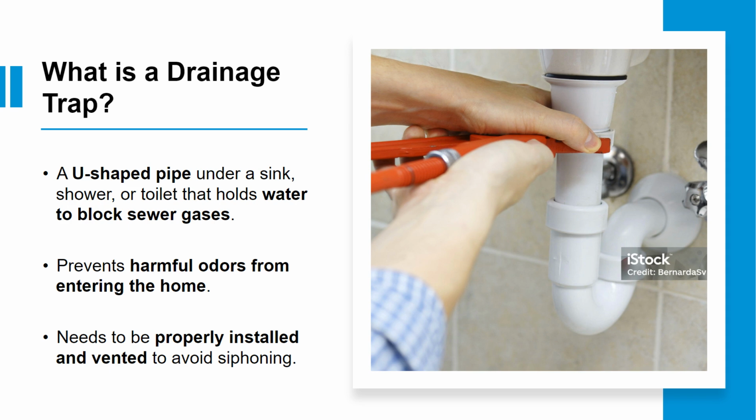Its purpose? To hold a small amount of standing water at all times. Why does it matter? That water acts as a seal. It blocks foul-smelling gases and dangerous sewer air from rising up into your home. Without a trap, your kitchen or bathroom would stink of sewage, and more importantly, you'd be exposed to harmful bacteria and gases.